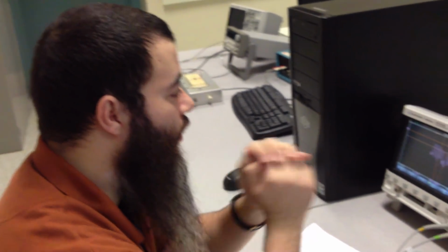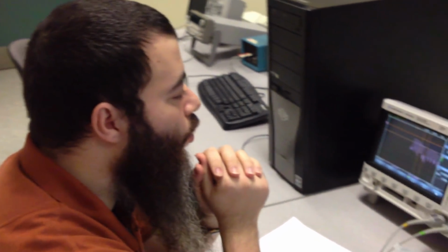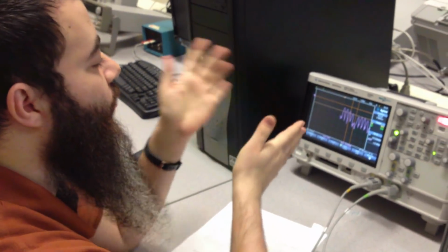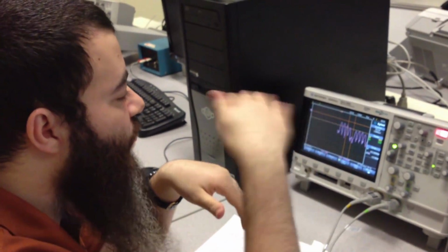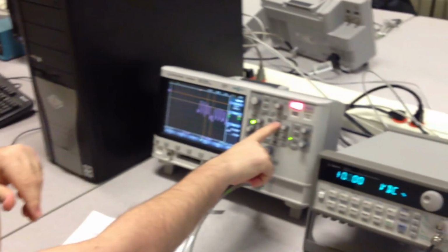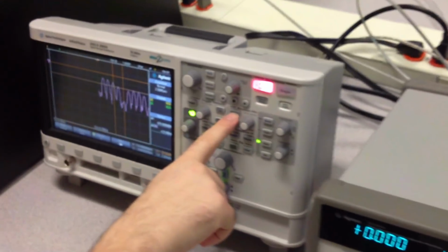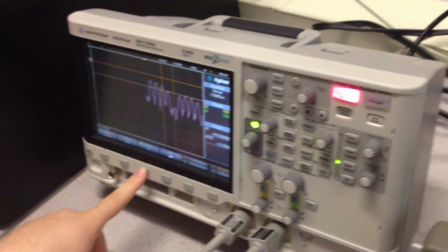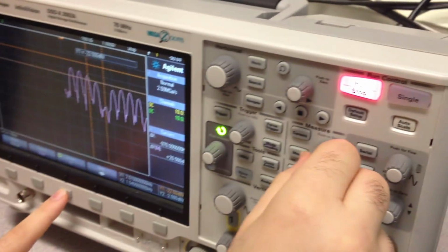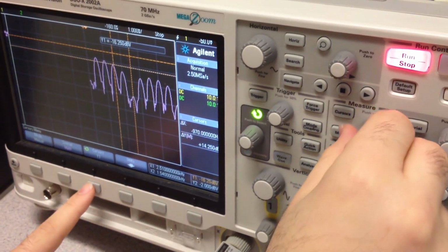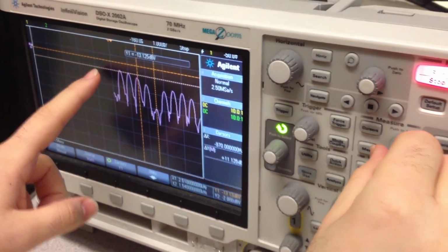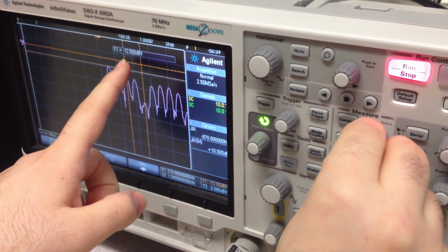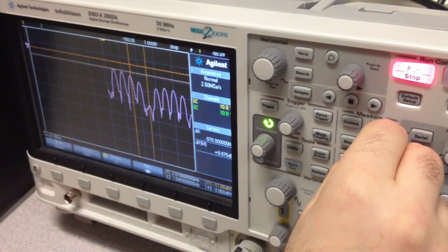Okay. So this is the frequency response. I now want cursors to check whether the vertical axis and the horizontal values are correct. If you look here, that's the cursors. When you press here, you get the cursors. Okay, let's take first the Y cursor. I could change the cursors from here. I'm changing the cursor here. So I get to the peak of the bin and read the value. That's negative 18.75. Write it down.